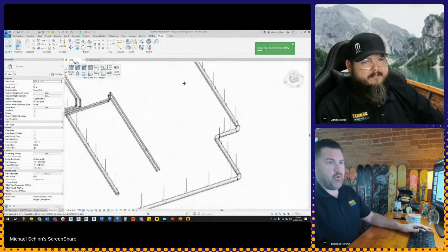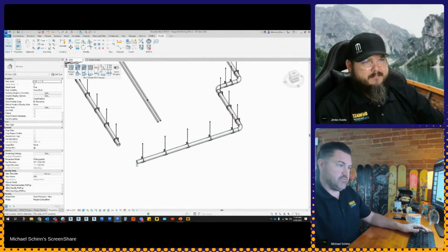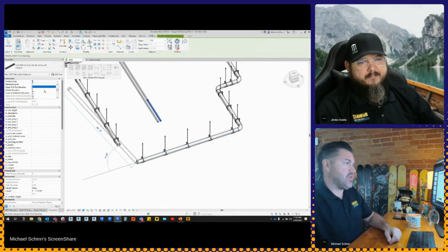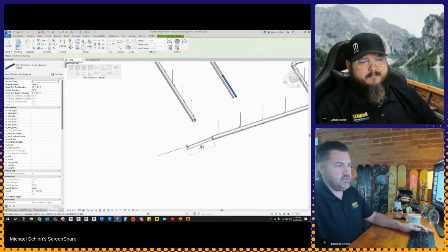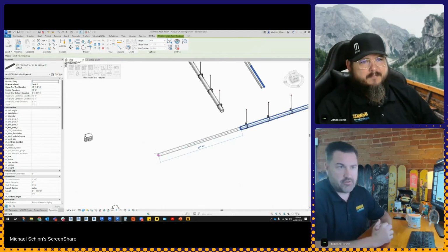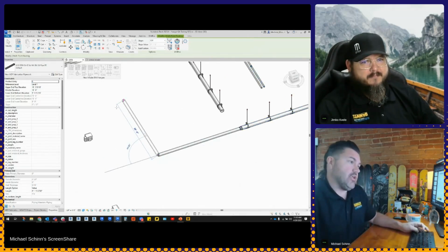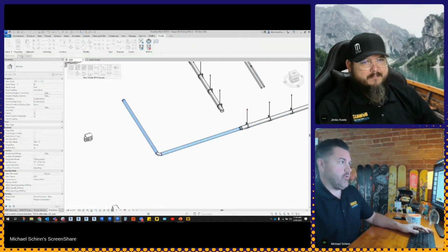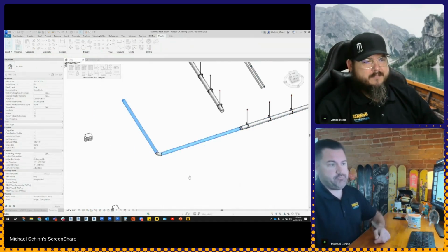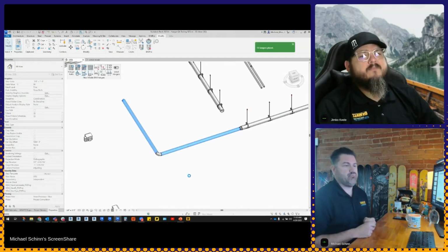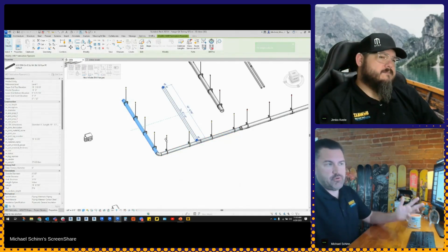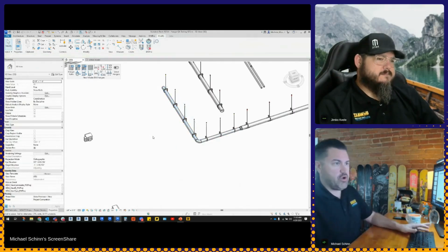Same thing here. If I were to also take this, let's go to here, right click, multi-point routing. It's at 8. Now let's drop down to a 6. Cool. And now let's keep drawing. And I can keep drawing and then simply click on and say, all right, well, I want to say hangers turn on. Done. 11 hangers added. Move this over. Cool. Coordination. Ready to go.